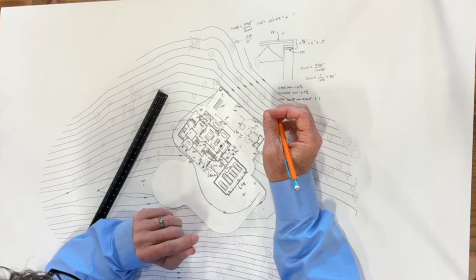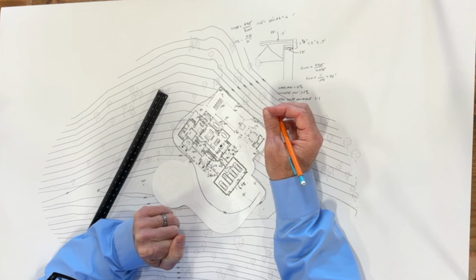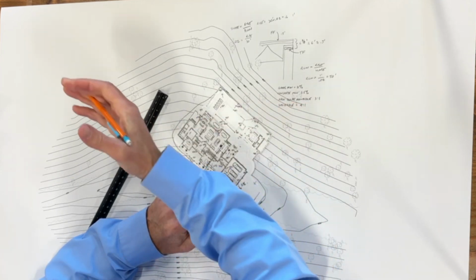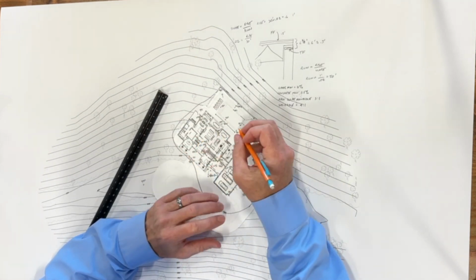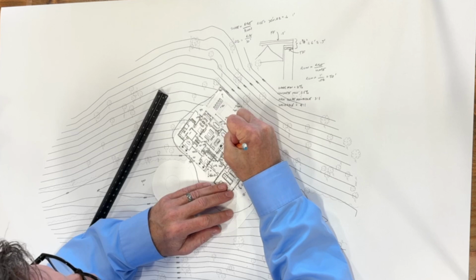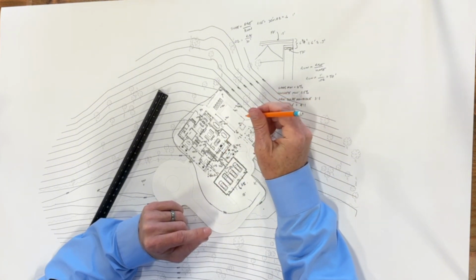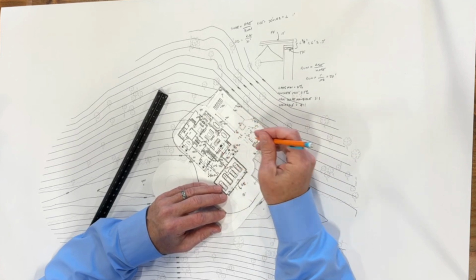I have 2 steps in there right now, but it doesn't have to. Gotcha. I'd rather it be 1 just so we don't create a low spot. So we make that 1. This also is where it comes in the architecture, right, of like how many steps you put at different places, because it all depends on what you're trying to drain. So that means the bottom of this 1 step will be a 940.5. Which is, you got to be a little tricky there or careful, because you got to make sure everything is not like ponding right there.